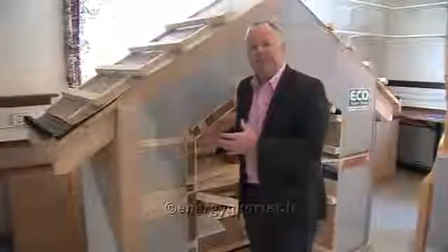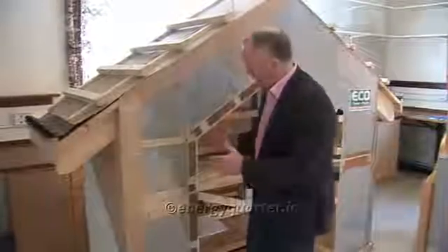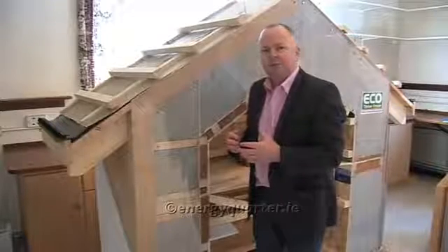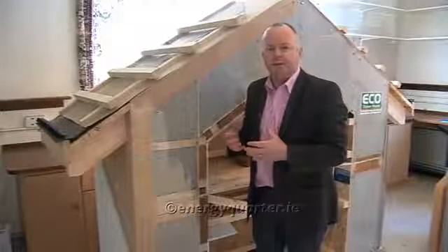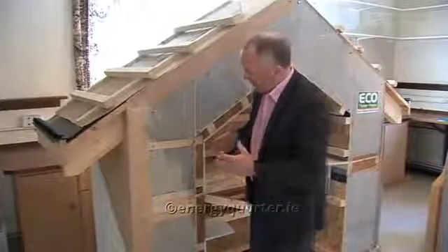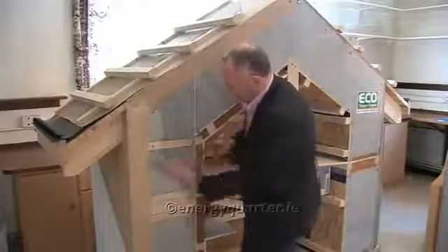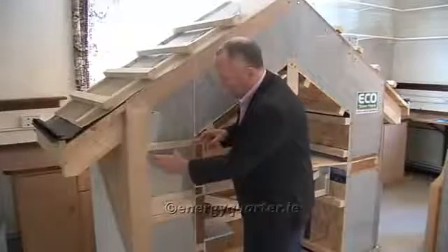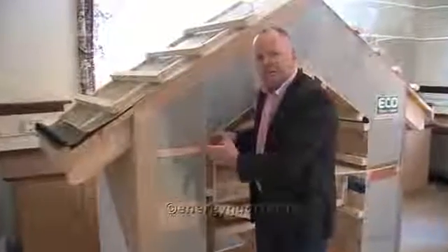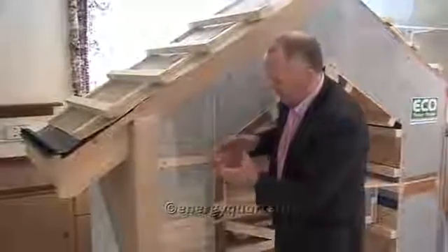One of the first things you'll appreciate from this is the amount of insulation that there is in this structure. We're talking about 400 millimeters approximately of insulation, which is probably double what you would get, or perhaps even more than double what you would get in a standard house. Looking at the cross section of the wall then, this part here is the main structural element of the house, so that's what keeps the house standing up. And you can see in this case it's filled completely with cellulose insulation, which is a very natural material and is blown in, so all the cavities are filled.